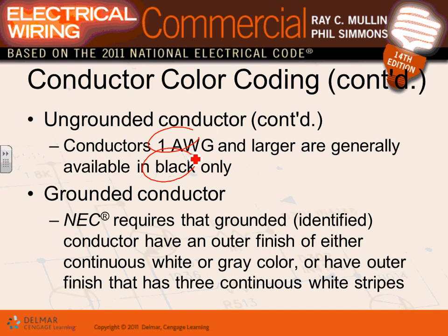So if you have four black conductors, guys, you leave one of them black, put red tape around another, and blue tape around the next, so that will give you three conductors, phase A, phase B, phase C. And the neutral is also another black conductor with white tape around it. So now you buy four black conductors, right? Because they're feeders larger than number 6, you can re-identify them in the field. So four black conductors, one of them stays black.